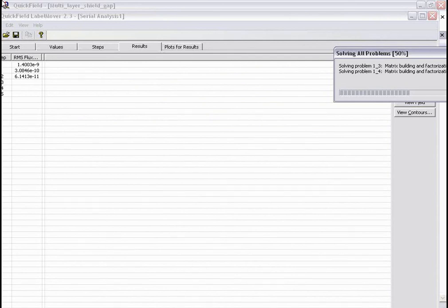Now the mumetal is great for shielding at low frequencies. We have a central layer of mumetal, and the outer conductors are going to assist in shielding at higher frequencies. So we're just modeling a few points here, and then I'll show you the result of a broader frequency range.